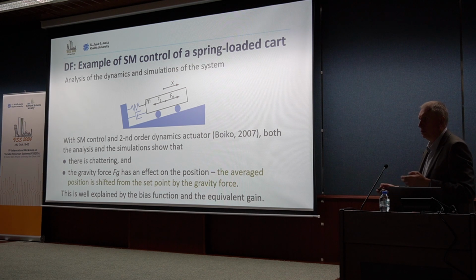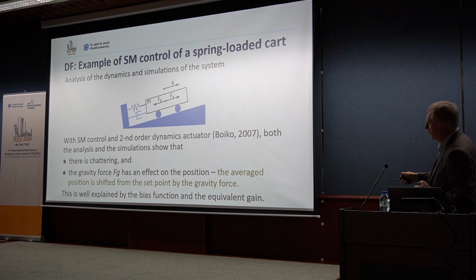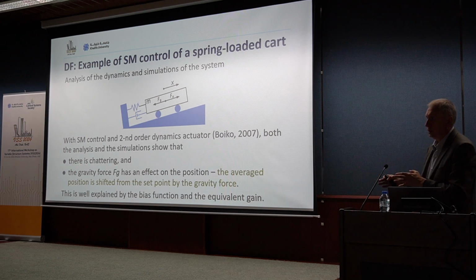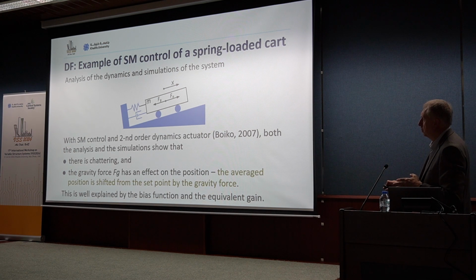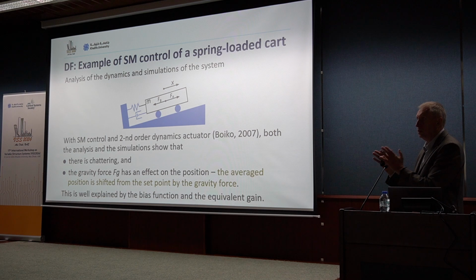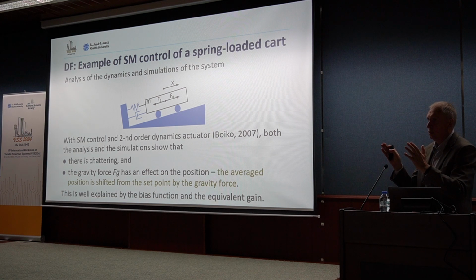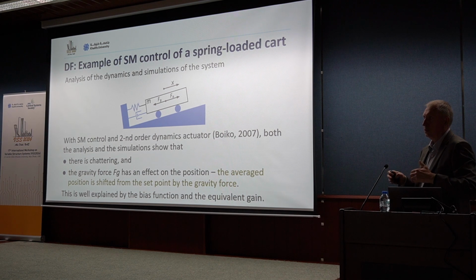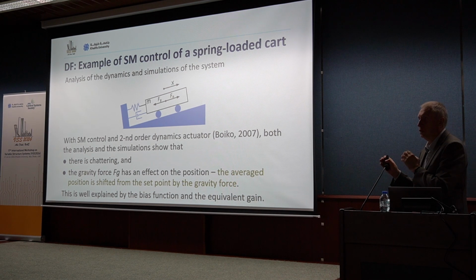As a result, we have chattering, but because of the gravity acting on this card, from the point of view of the ideal sliding mode, if we had an ideal sliding mode, we should not have the displacement of this card down this surface, because the sliding mode control would reject this disturbance, which is the gravity component.